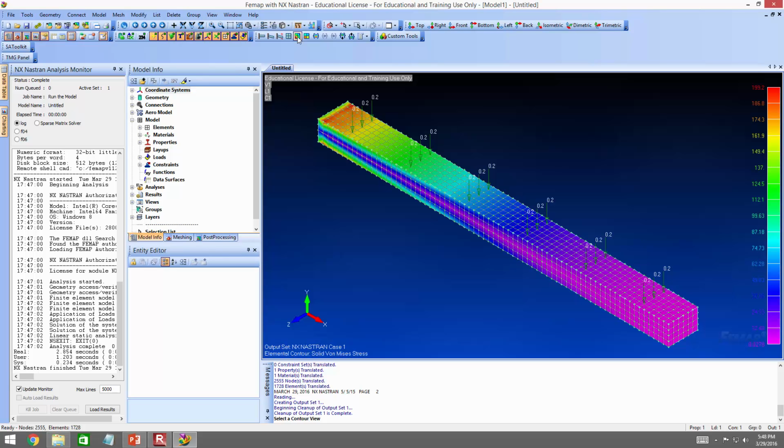Okay, so this is the response of that beam. What are these magenta purple values representing? What's the stress like in those areas? Pretty much nothing, right? They're almost zero, right? But remember back to your structural analysis. If you've got a cantilevered beam, you don't have any moment right here. Your moment on a cantilevered beam is highest where? Back here. And look what you've got. You've got your highest stresses on the top and the bottom. Remember, bending stress, highest on the top, highest on the bottom.